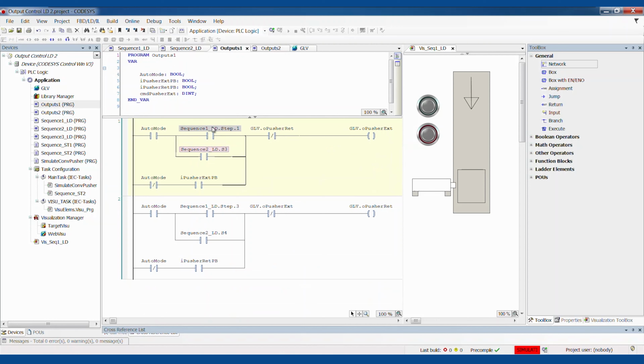For example, what happens when I want to run this output from many places, from 10 or 20? That does happen, I've seen that, and it's pretty atrocious on ladder logic because it just runs right off the screen. It takes a lot of scrolling to capture that whole single rung, that simple idea of, oh, these things make that thing go. And I try to stay away from that. I don't like monster rungs. It's not always avoidable. Sometimes that's just how the language works, but I try to avoid them, and we're going to talk about a good way to avoid that today.